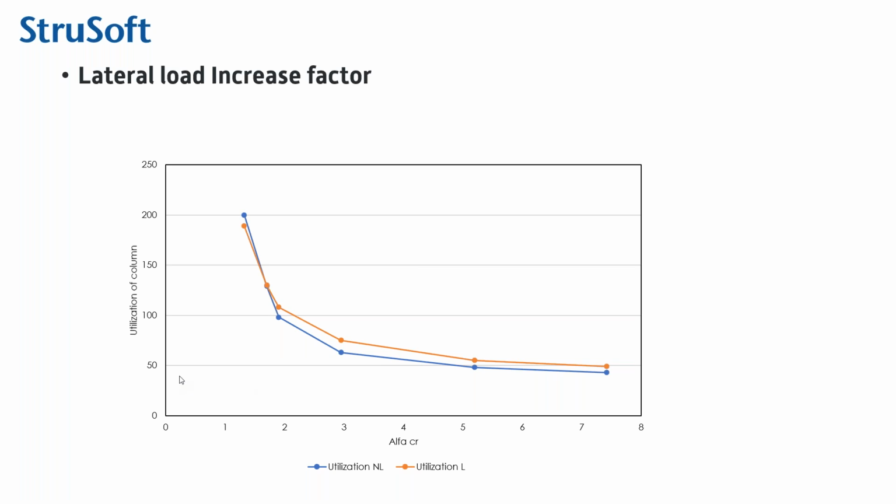Question: how do you combine these curvatures with your load combinations? I always include them in a load combination, and you usually put them in the same direction as your wind loads. If you are uncertain, you can do plus and minus. So wind load from the plus x direction plus the deviation in x direction, and wind load from the minus x direction, and combined with the eccentricities in two directions.